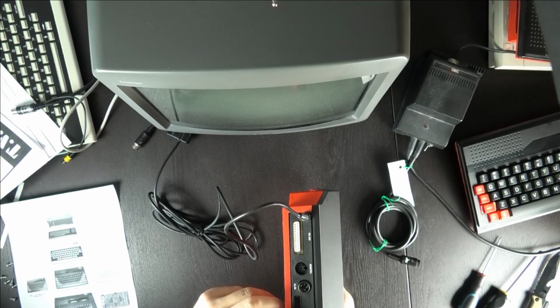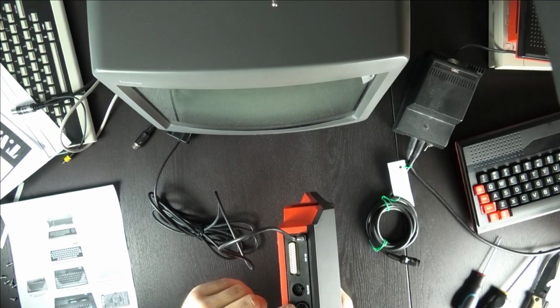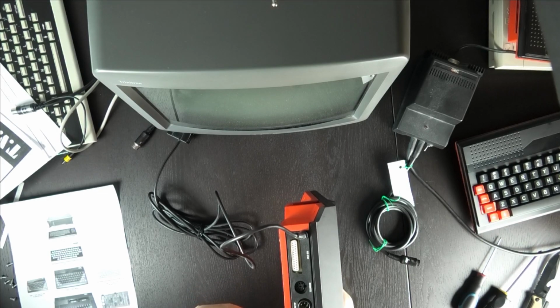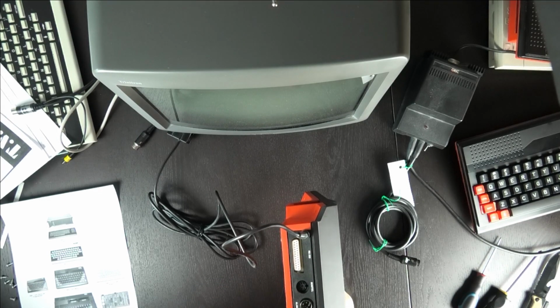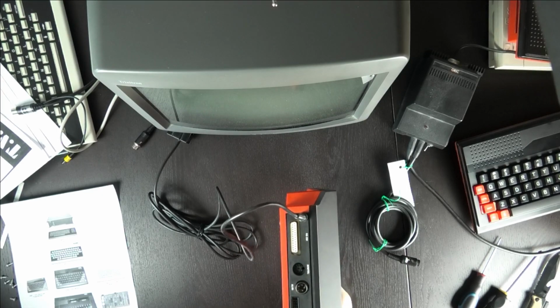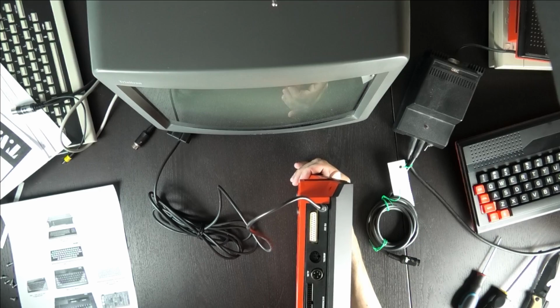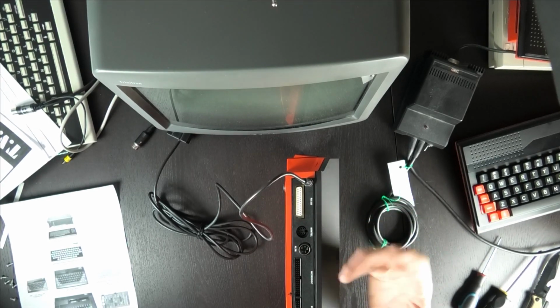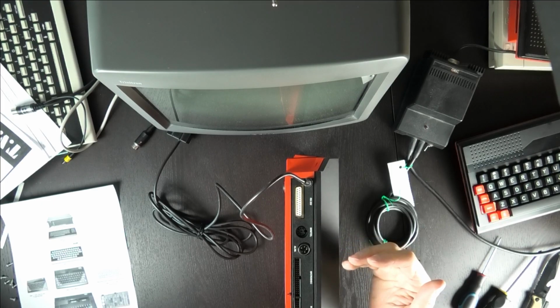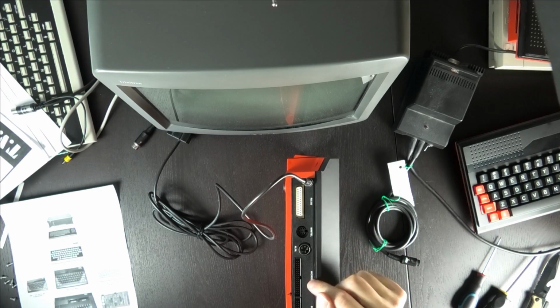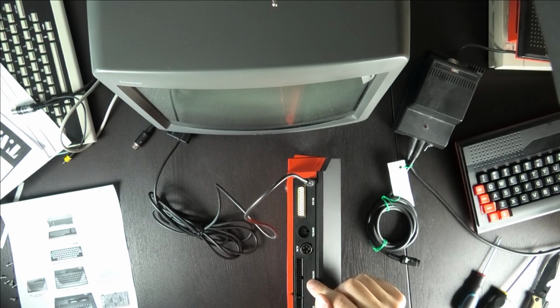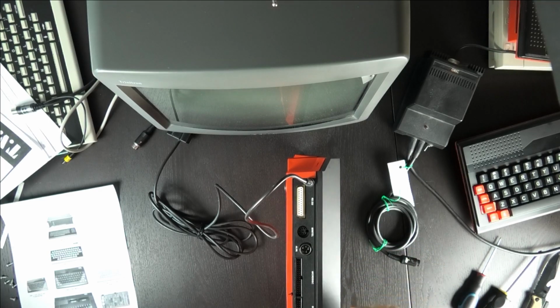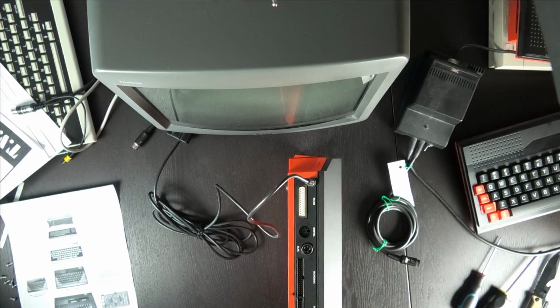Many micro disks on Telestrat have been killed because of this and that. These connectors are very similar to these ones, and the Oric Atmos came with two types of micro disk, the slave and master. The master unit has a controller, like what is inside the Telestrat, while the slave are just dumb drives that you can just plug. So on the Telestrat you should only use slave drives. If you put a master drive which has the same connector, you're going to burn one of the controller boards, or some RAM chip, or bad things are going to happen.